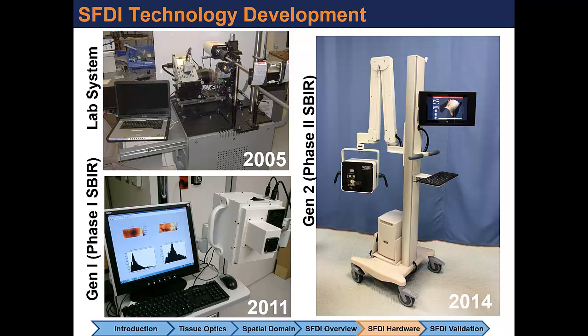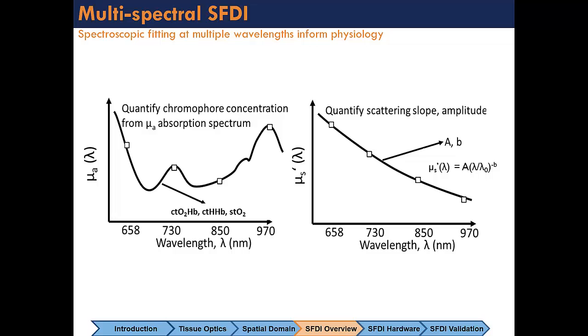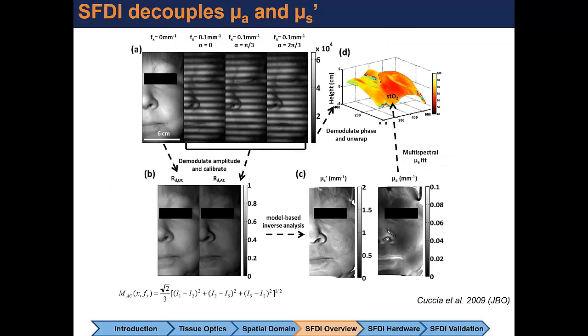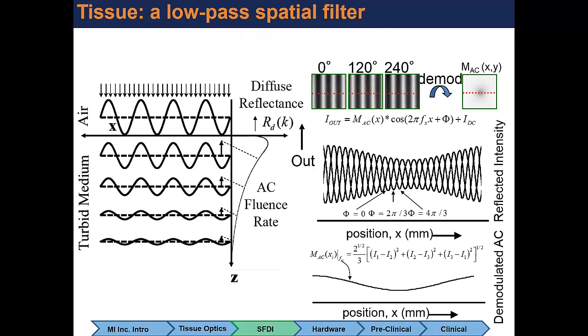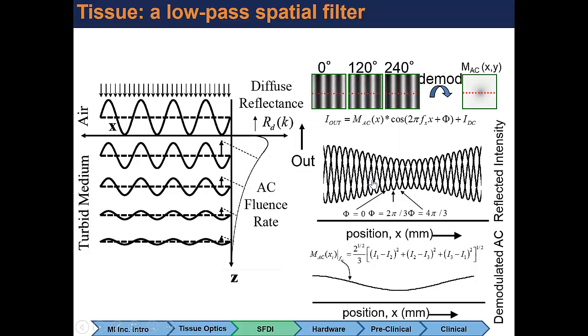Yeah. So why do we do multiple phases? First of all, it's one way to calculate the envelope. This is historically a time domain approach where you phase delay in time three waves coming through wires, and then you use circuitry to do this math in hardware.